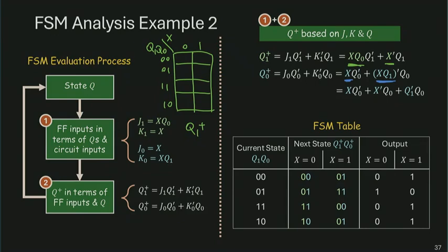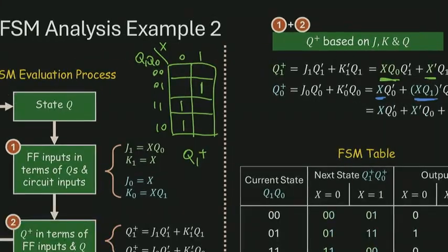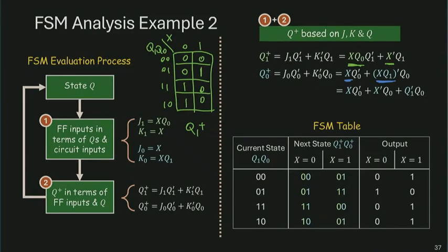And the X equals 1, so I have a 1 over here. And X equals 0, Q1 equals 1, which are these two ones. And that is my K-map for Q1 plus. You can put that column at this part, the left part of the state table, right, which matches exactly to that K-map. 0, 0, 1, 1, 0, 1, 0, 0 on the two columns.